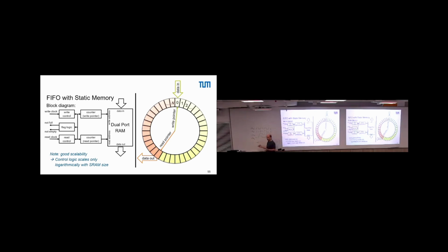You can, of course, try to transfer this clock signal. You can say, I send a write clock along. If you do this, and system B operates fully on that clock, you're fine. The two systems are effectively synchronized. That works, but frequently you don't want this.